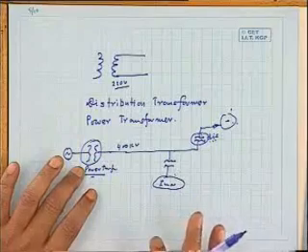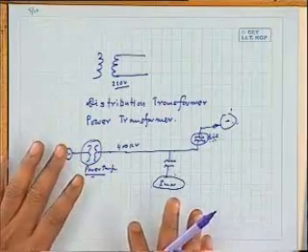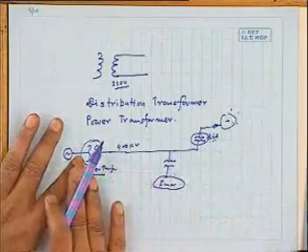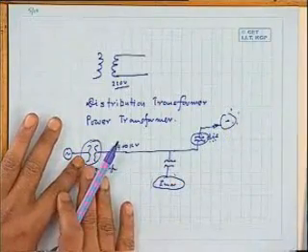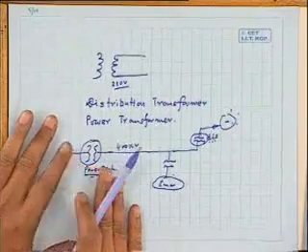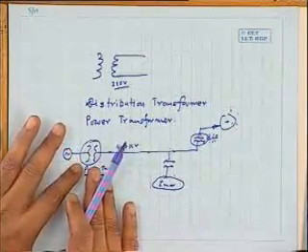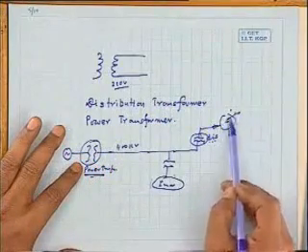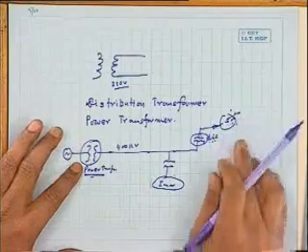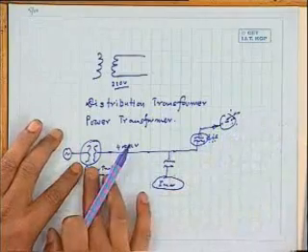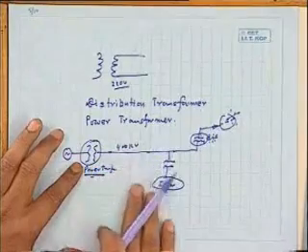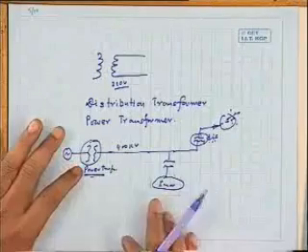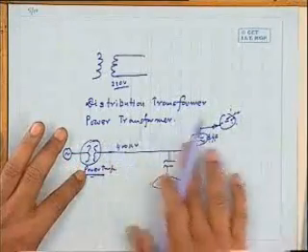If you look at the loading of this transformer, it is not really undergoing any no load condition. The sum total of all the loads will be handled by this transformer, and if its capacity is say 100 MVA, whether this fellow is there or not, this load is there or not, it will hardly matter to the secondary of this transformer, because the bulk load is your industry load.